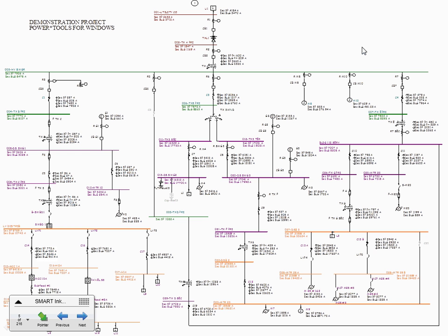You only show major equipment, like 30 horsepower or more, and 100 amp panels or more. You don't show branch circuits. You show major equipment, 30 horsepower or more, and 100 amp or more, in here. So who cares? Here's my, I don't know if it's going to show. Oh, it's right there. I don't know if you guys can see this one. This is the short circuit capability coming in and going back into Excel.